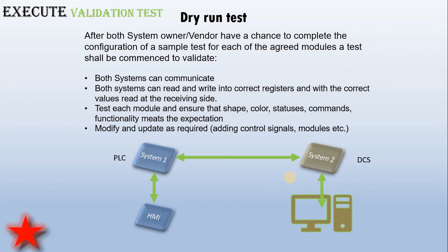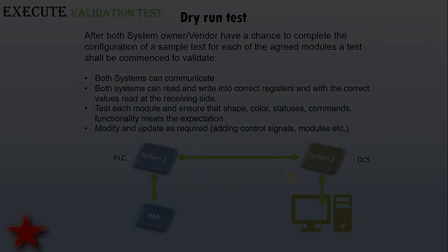Do you need an extra bit for releasing the control and releasing the whatever? Try to see how you acknowledge the alarm. Do you acknowledge the alarm in this DCS? How does it happen in the PLC? Once you tweak those sorts of things a little bit, then you can go ahead and build your system. This will make everybody's life easier.